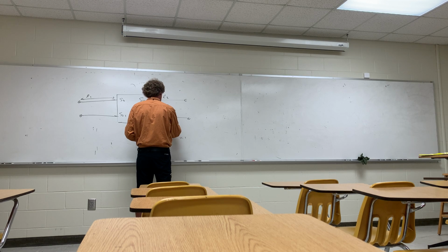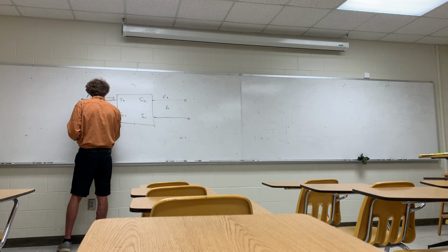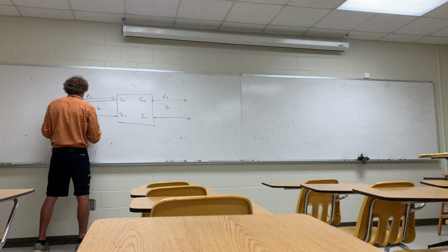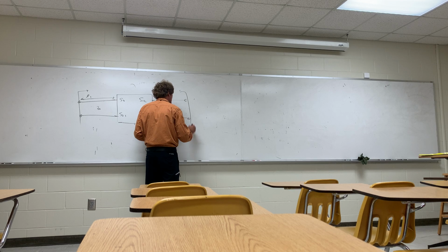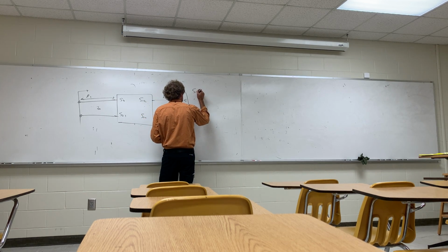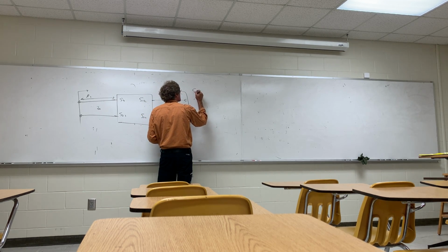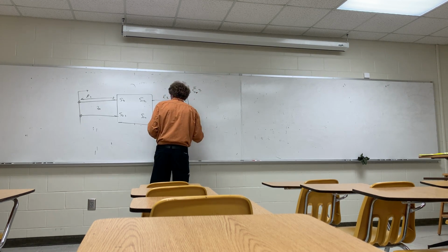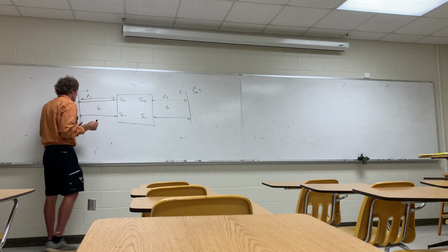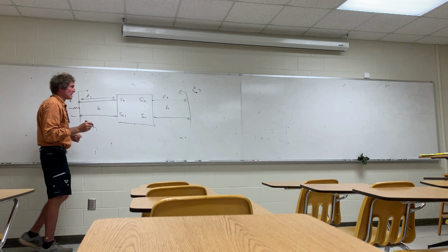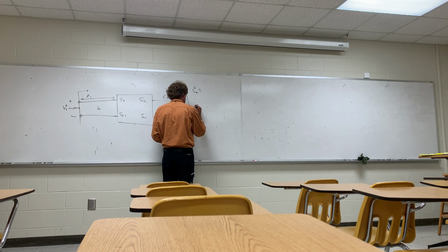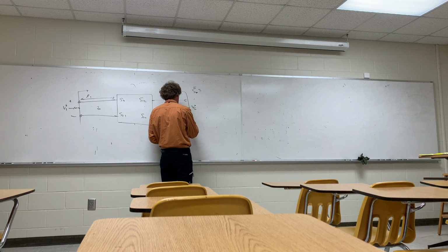And we're going to assume these are matched, so this is going to be Z0 and Z0 here. And now I want the S parameters for this entire network. So now I want the shifted S parameters, and I'll call it S reference, we'll call it that. So how do we get them? Well, remember, my signal V1 plus is coming in at this port, and my signal V2 plus is coming in at this port.